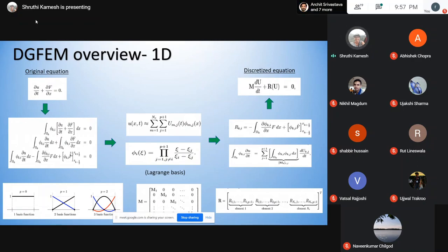For example, if you have a solution with many shocks, you would expect better results using something like a Roe flux, which is a very elaborate way of accounting for the discontinuities on the left and right to model how the elements interact with each other.